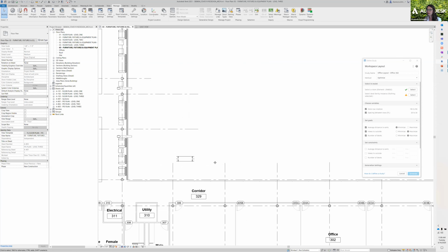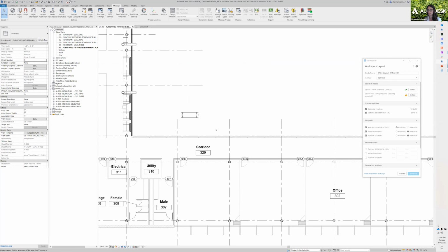Now, when we think about how this operates in the era of COVID, I know from working with it before that this script and algorithm is going to create a benching layout, stacking the desks end on end for high density. When we think about safety and social distancing, that might not be something we want. So we have a couple of different options. The first is to modify the script. Everybody has access to this: if you have the generative design tool, you have access to the algorithms it's running on, so you could go in and edit it.